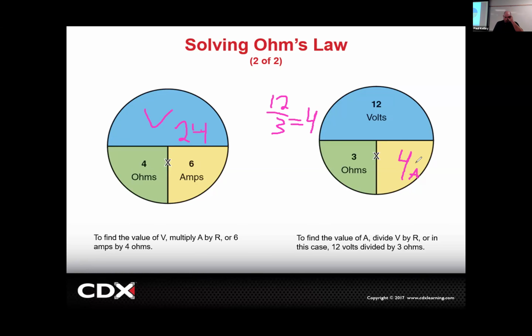And if you were to do this on the boards, you'll find it's generally true, but there's one thing I have to warn you about. We are talking about the ohms right now. And what we learned in the theory was, remember, when things get hotter, what happens to their resistance? It goes up a little bit, yeah. So when you measure the bulb, if the bulb is 3 ohms, by the time you actually get it hot, it might be 5 ohms or 10 ohms or something.